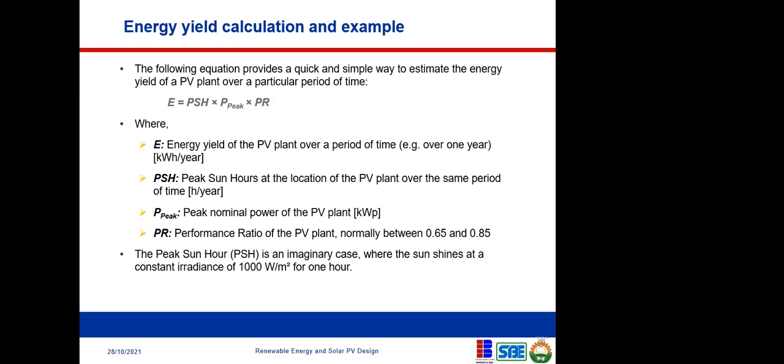So if you're doing 400 watts per meter square for 8 hours, and then push it to 1,000 watts per meter square, to find the peak sun hour you do 1,000 times 8 divided by 400. Can you do that and tell us what the answer is? 1,000 times 8, that's 8,000 divided by 400.